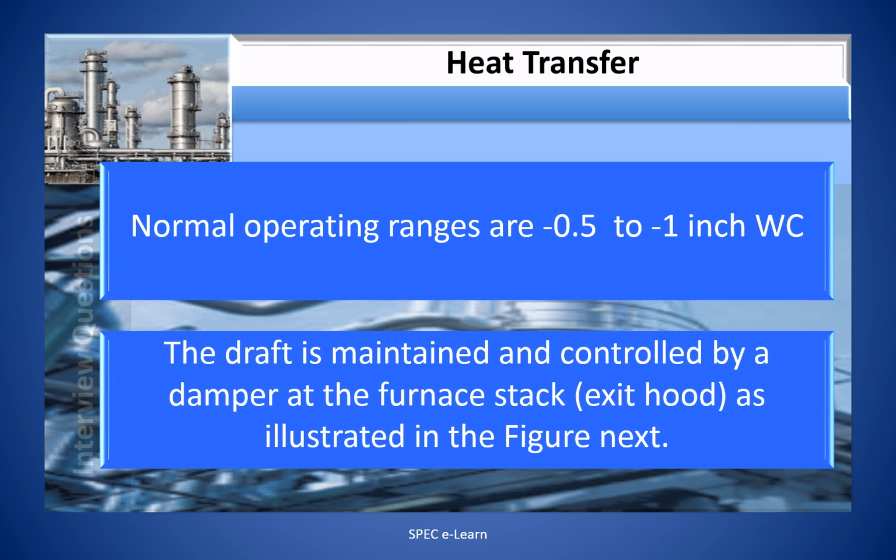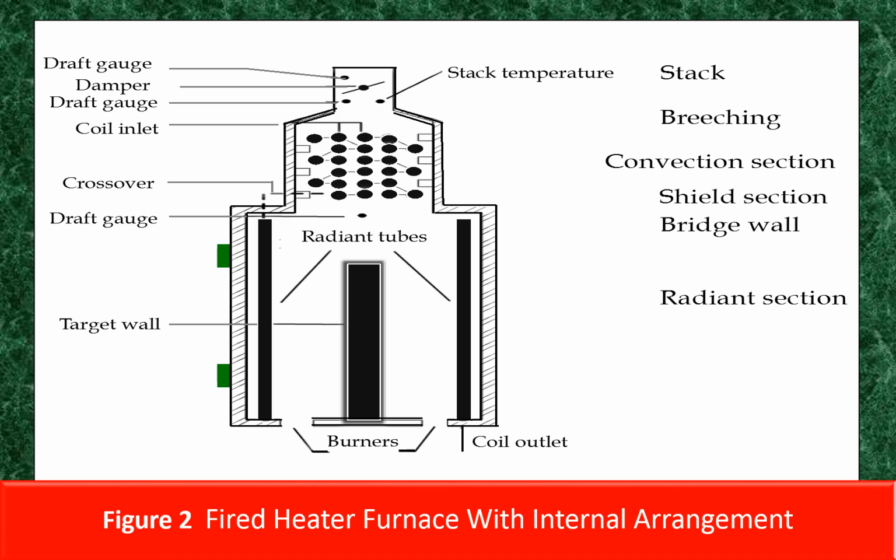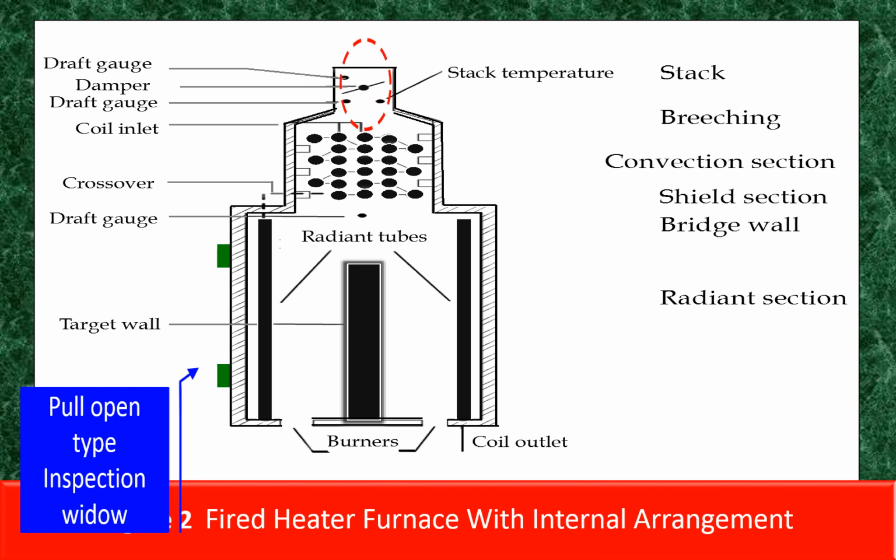The draft is maintained and controlled by a damper at the furnace stack, that is the exit hood, as illustrated in the figure next. This figure illustrates a fired heater furnace with the internal arrangement. Observe the burner mounting and the inspection windows, as well as the damper control and the location of the draft gauges.